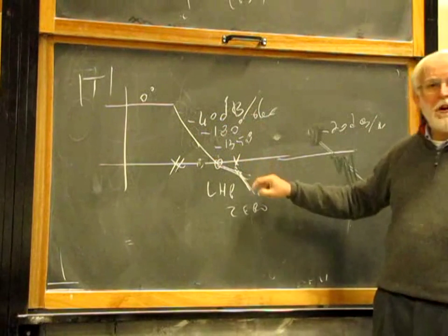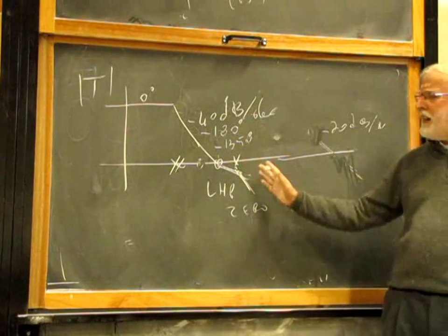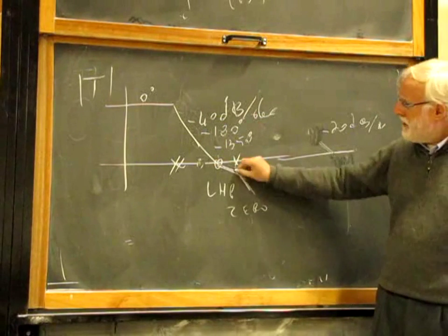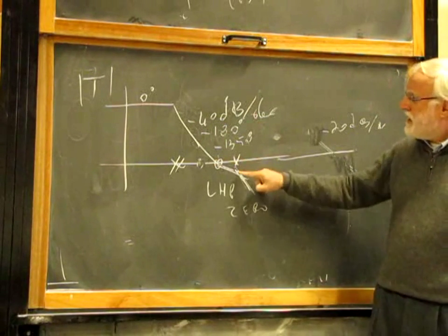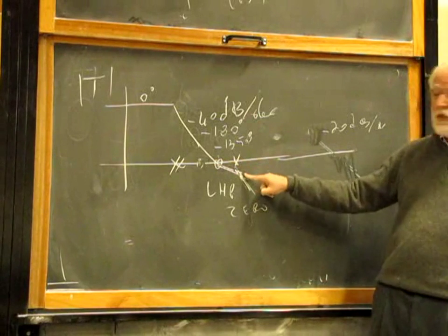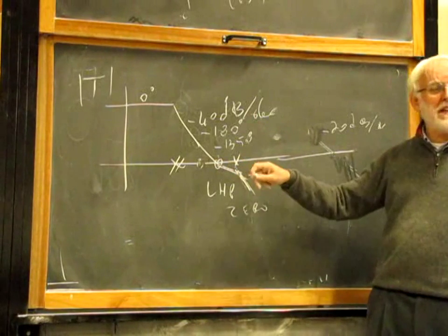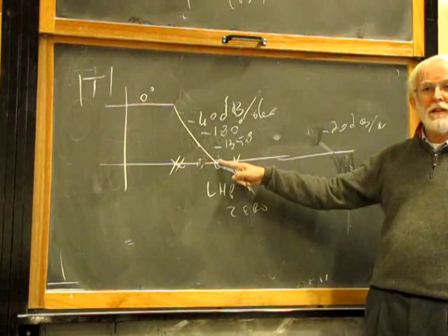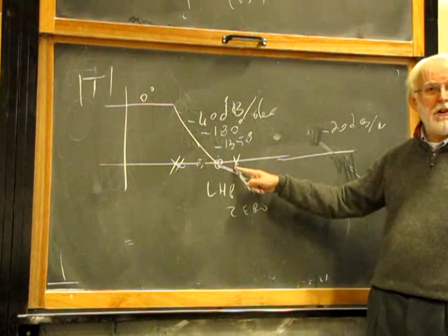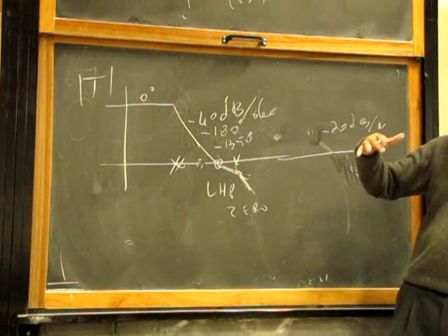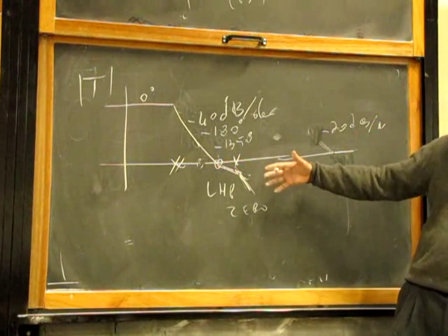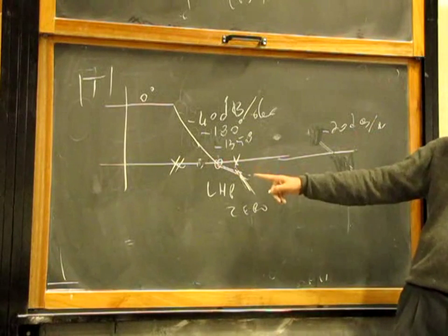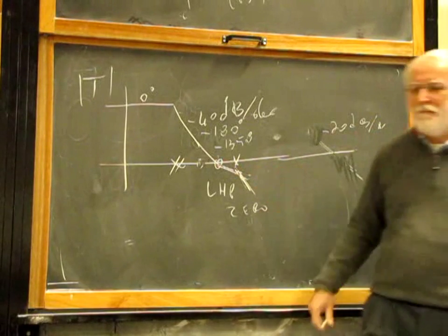And here we have another pole, it's after the crossover. If it is far enough, it does not make any noise, any mishap. But if this pole that is beyond the crossover frequency is not too far, let's say it's just a factor of 2 above the crossover frequency, what we get is that this pole just decreases my phase margin. But probably it's still stable. Okay? Stable or unstable? Reasonably stable, probably.